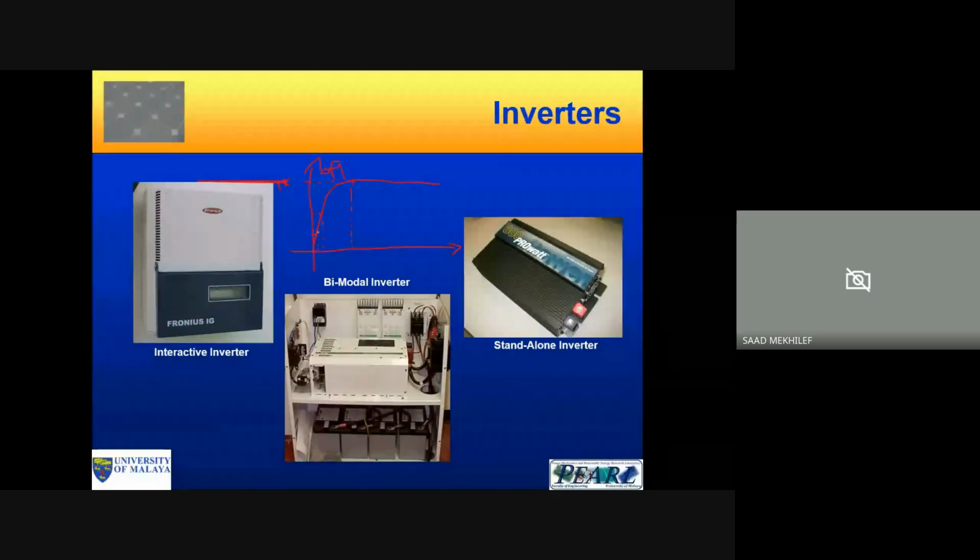In real systems we include the losses, from the PV panels to the DC-DC converters to the inverters. So the inverter should be lower by 20%, not more than 20%. Why? Because we want the inverter to operate at its rated power, to achieve maximum efficiency.